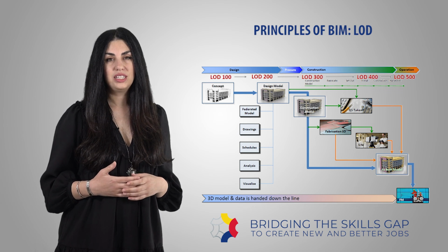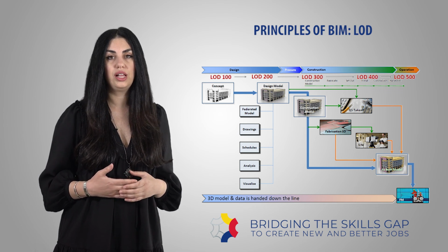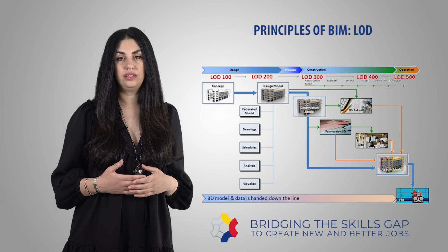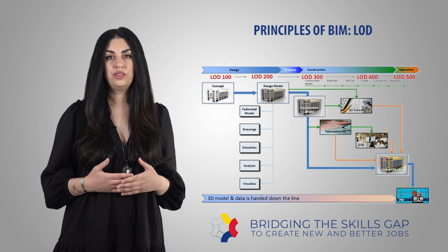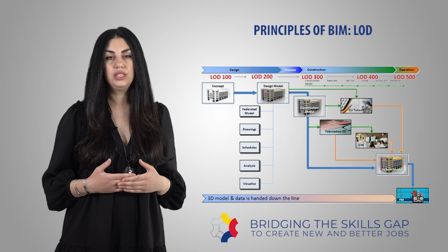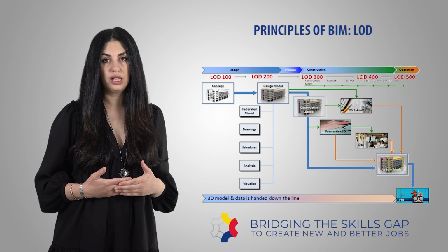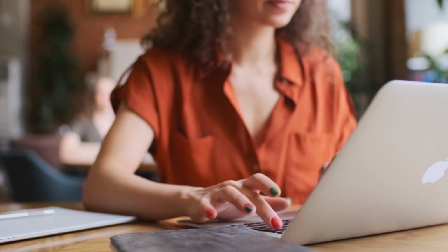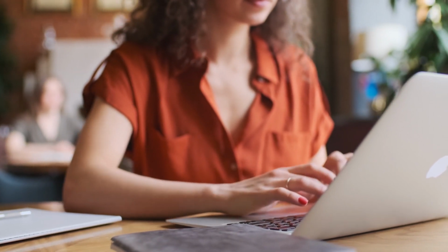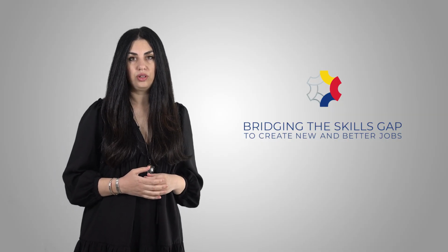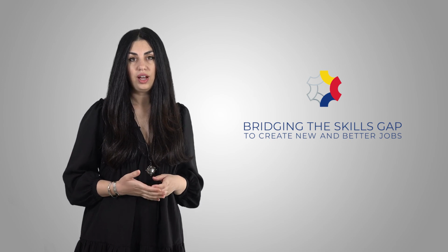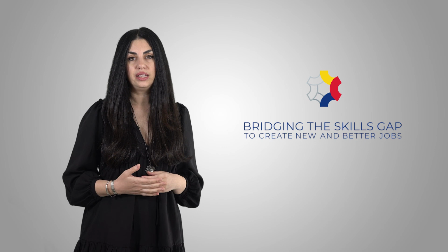Here's my opinion. It's not so much about using those official LODs. I mainly use it as a guide. What's really important is to define, according to BIM use, project phases and delivery, the level of detail and information for each object, and as soon as possible in the process. You wouldn't need the same amount of information regarding analysis, simulation, visualization you want to run. This way, it will allow you to efficiently build your model that fits your budget. Otherwise, you could spend a lot of time making everything in detail.